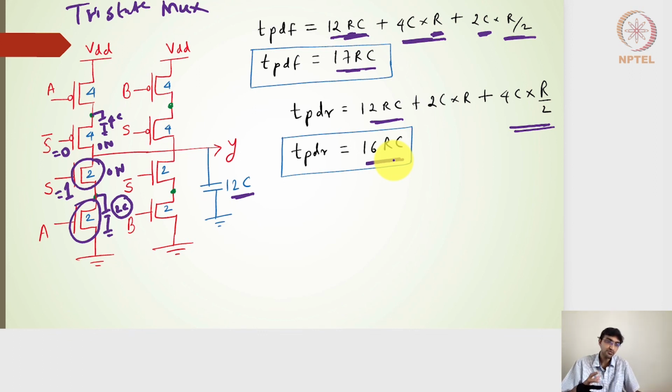So we have two different multiplexer designs: one is the tri-state based, and another one is the transmission gates. The layout of both of them will be very, very similar. The advantage with the tri-state multiplexer is that the metal line is not there, so additional two metal lines don't come into the picture, which is good in the sense that additional metal lines will cost us a little bit more.